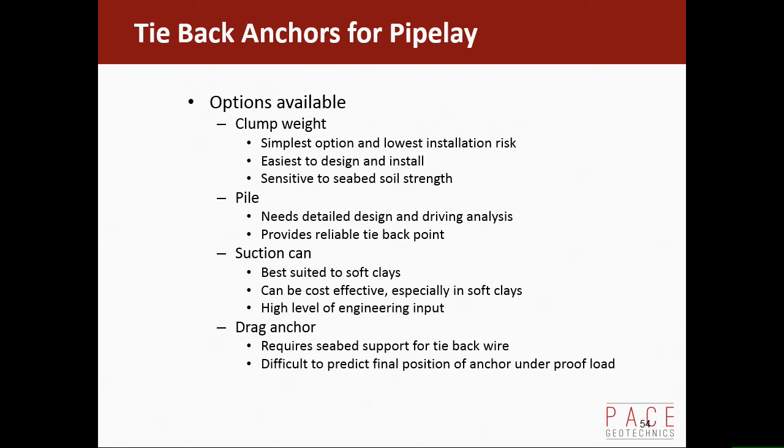The suction cans do work well in soft clays, and the advantage is you can usually get them out, especially if you designed it as a hold back anchor. I know some people have one or two on the shelf in the store yard, which they've used on several occasions and moved from job to job, or within a job, to hold back pipelines when they've been laying them. And then a drag anchor,